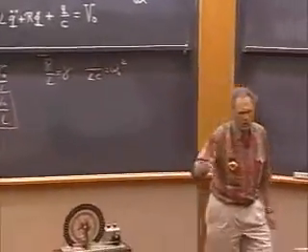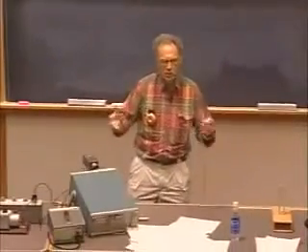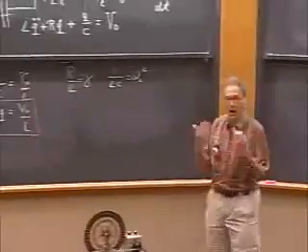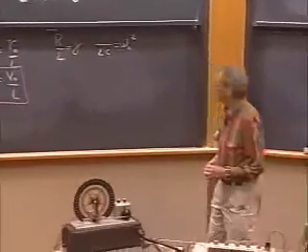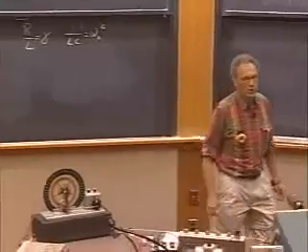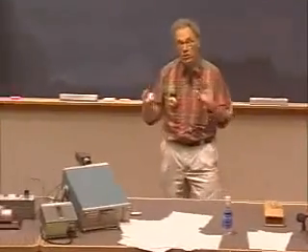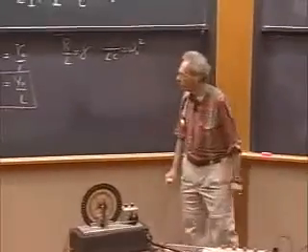The larger R is, the more heat dissipation there is. Heat dissipation goes in terms of I squared R, and clearly that means you take energy out of the system, so that means there is damping. And this is then the natural frequency of the RLC circuit if there is no R. If there's only an L and a C, this is the square of the frequency.